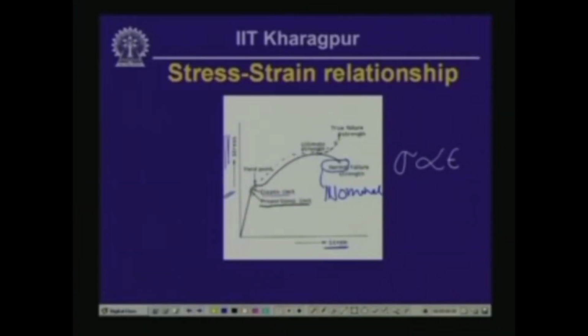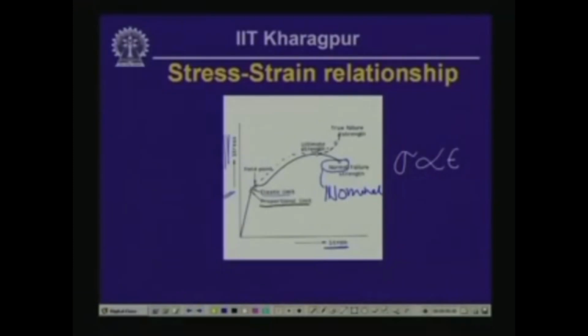If we keep on applying load at that point, in fact without increasing the load, the bar deforms, the extension becomes excessive, and it reaches a stress which we call the maximum stress, and there is a loading down on the load when the bar fails, and that is how we get a failure stress which is lower than the ultimate stress. So, this is the maximum possible stress that a bar can attain, which we call the ultimate stress, and this particular point is the failure stress.